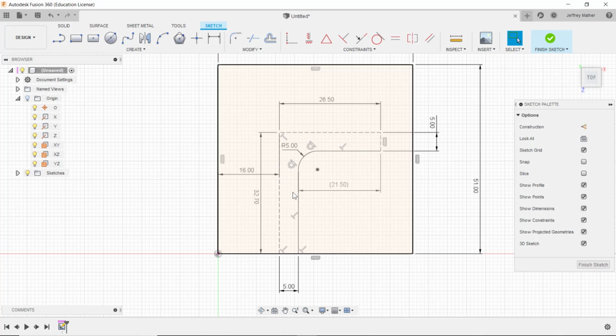On your sketch, it looks like you have the same radius here and out here, but for an equal distance, you would offset this, and it wouldn't be the same radius. From here over, it would be 5 millimeters bigger, or a total radius of 10. But I think your sketch is a little bit off in that respect.